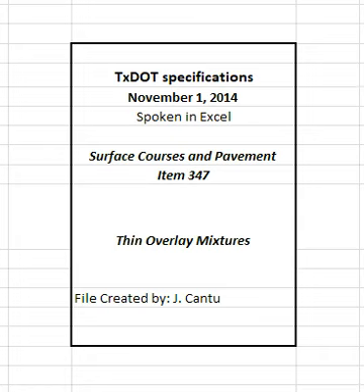4.1 Certification. Personnel certified by the department-approved hot mix asphalt certification program must conduct all mixture designs, sampling, and testing in accordance with Table 4. Supply the engineer with a list of certified personnel and copies of their current certificates before beginning production and when personnel changes are made. Provide a mixture design developed and signed by a Level 2 certified specialist. Provide Level 1A certified specialists at the plant during production operations. Provide Level 1B certified specialists to conduct placement tests.